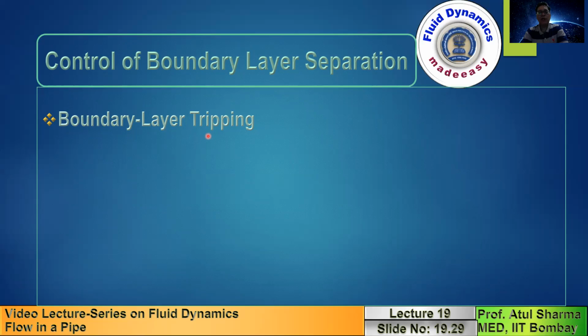And if you compare the laminar boundary layer versus the turbulent boundary layer, the turbulent boundary layer, as I mentioned earlier, has much larger acceleration near the wall. So the flow separation in a turbulent boundary layer, as compared to a laminar boundary layer, is delayed. So when you consider a cricket ball, when the transition takes place across the seam and the fluid passes through the rough side, the flow separation on one side is delayed, and that leads to in-swing or outswing.